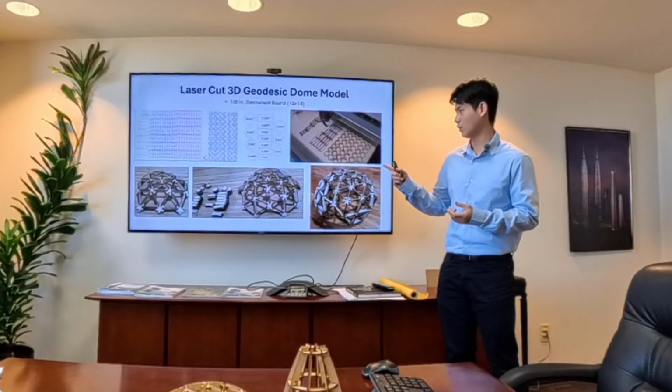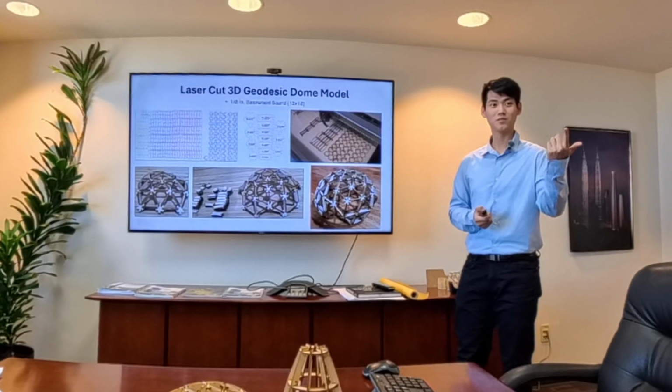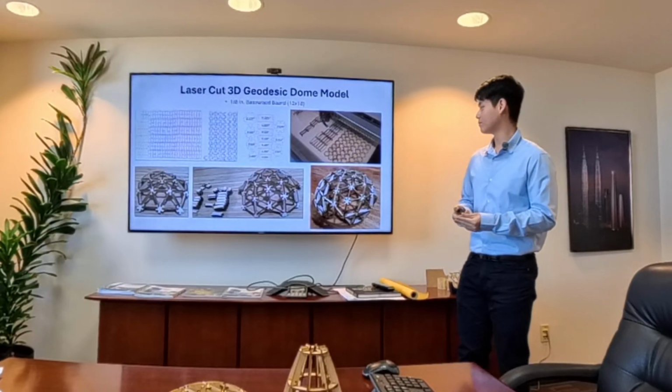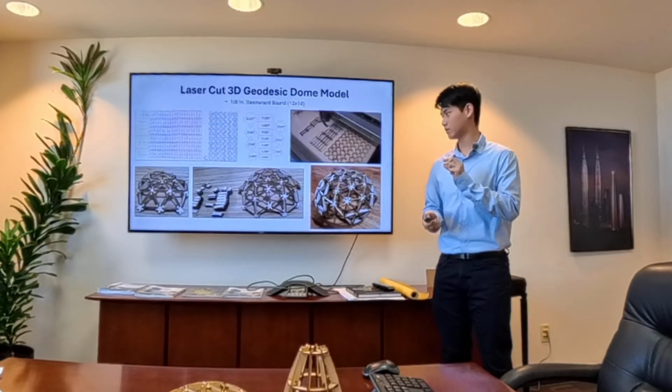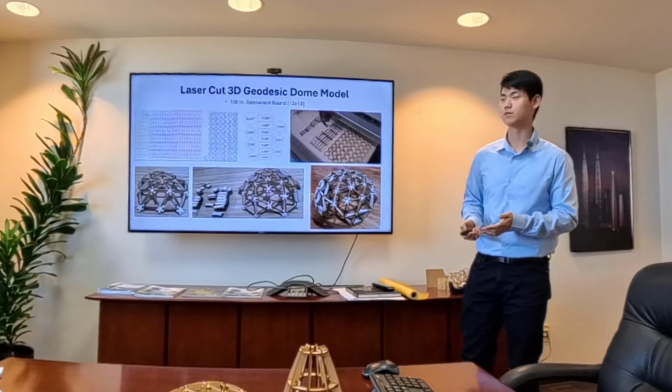So, although this one, sorry. Tolerance, you mean? Yeah, the tolerances, but also the kerf of the laser. So that's two things you need to account for. Although this one came out pretty well, there was still a little minute gap in between the connections, so we took that into account for the future.